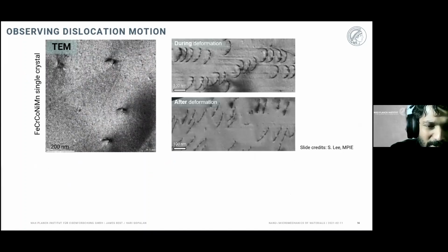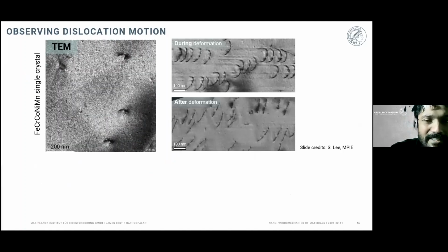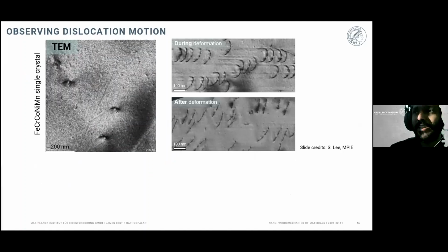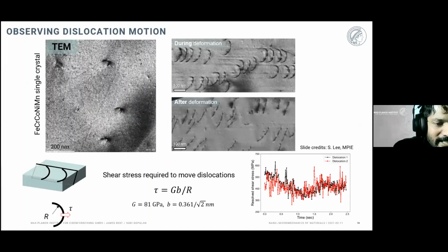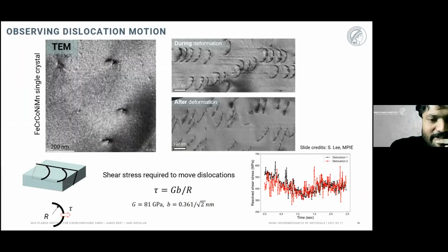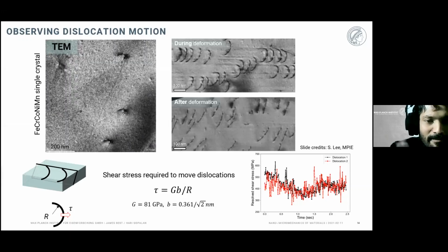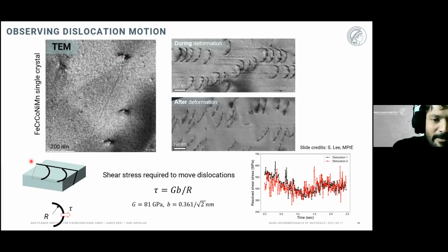And you can use a transmission electron microscope. When the electron beam falls on the sample, these localized strain fields take you away from ideal diffraction conditions. And you see these things as dark bands or curved regions. So these are, in effect, the dislocations that you see by their strain signature. Now, it's nice that we can actually observe, as we pull on a little metal piece of sample, these things moving under the influence of stress.